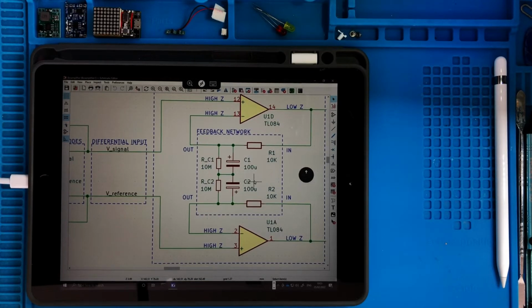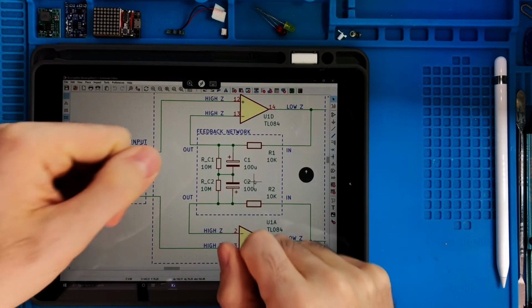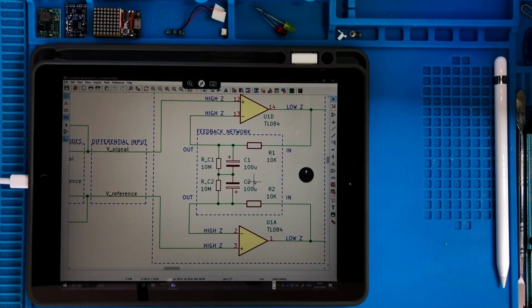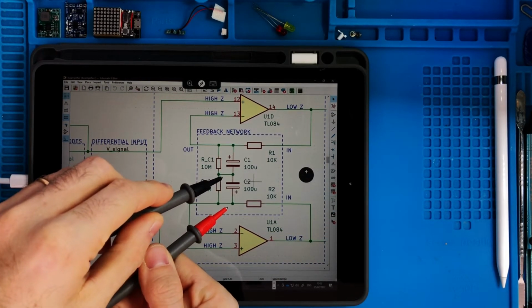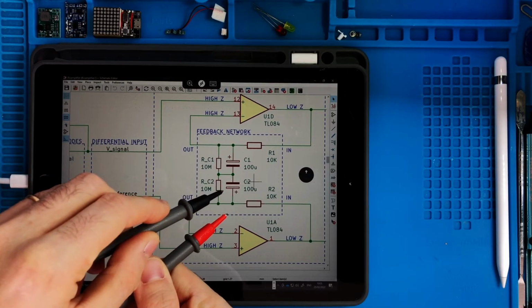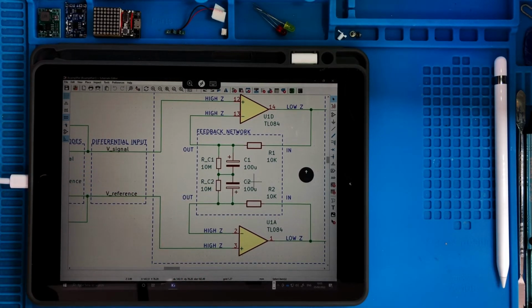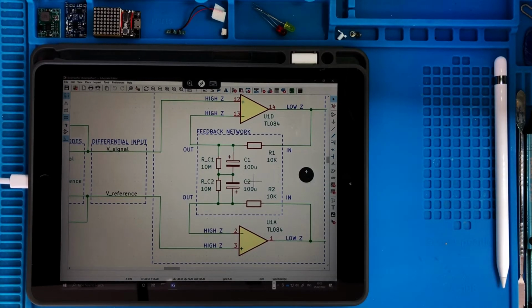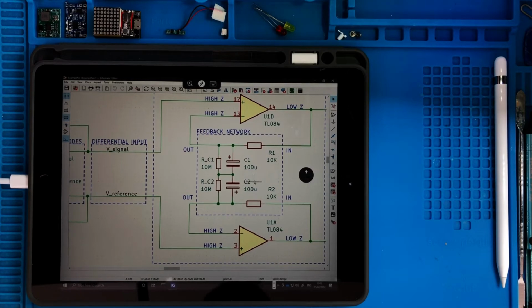So if I apply a battery across a capacitor, like this, if I charge a capacitor, then when I remove the battery, the capacitor will stay charged. So there is an initial state of charge of the capacitors that will influence the time simulation. And so all the capacitors need to reach a steady state in order to have a steady signal at the output.